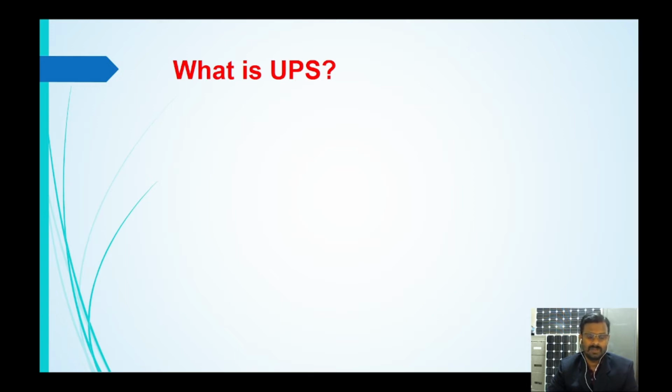Usually, the UPS is used for a short time period. This short period is used to change over from the utility supply to another source, which could be the battery or other sources like a generator. During this short period, the UPS should provide the power so that the system will not shut down without saving the information properly.